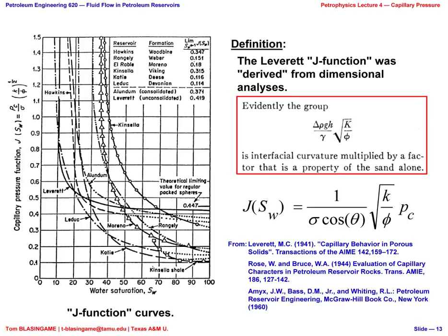And that means we're going to have to define another dimensionless variable. Remember, dimensionless variables are the variable divided by their characteristic. And in this case, the characteristic pressure we choose is displacement pressure. The characteristic saturation is irreducible saturation. But there's a trick, because irreducible saturation doesn't represent the movable pore volume. 1 minus the irreducible saturation represents a movable pore volume.